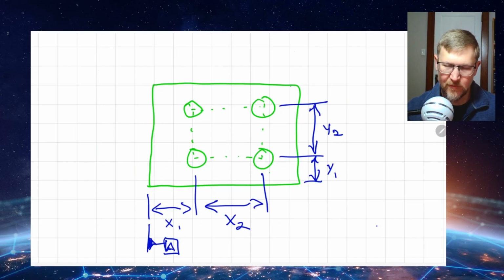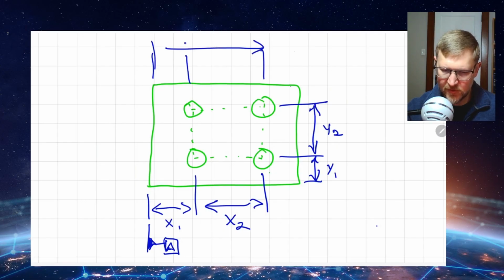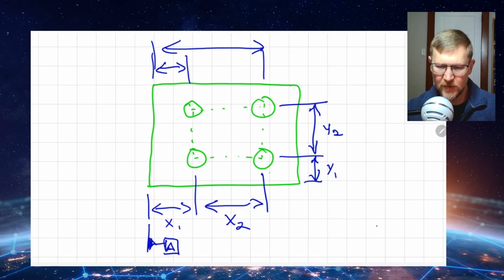And so if you have a pattern like this, you may want to make sure your fasteners or your holes are located relative to each other, and not something where you might have, for example, a dimension set like this, right? Because it's not so much critical that the holes be positioned relative to this edge as much as they be positioned relative to each other.